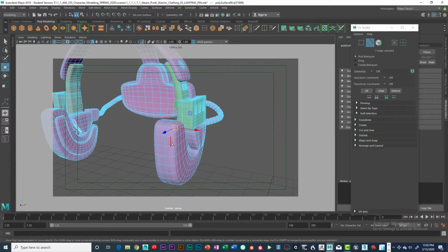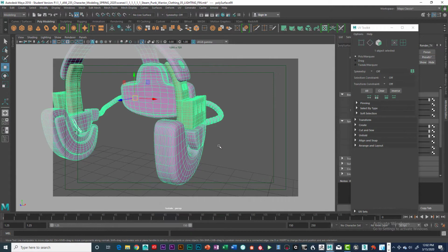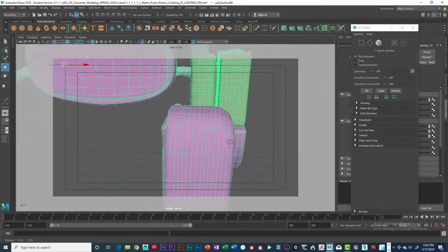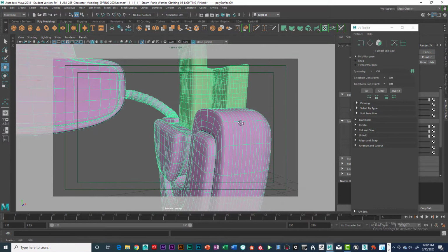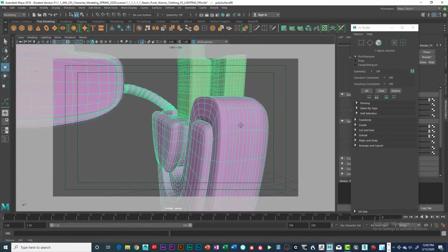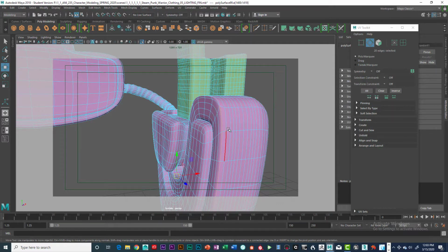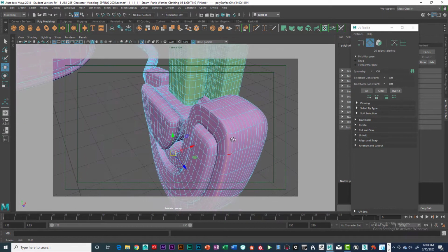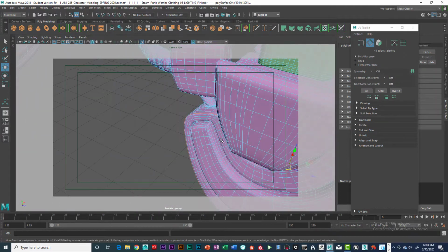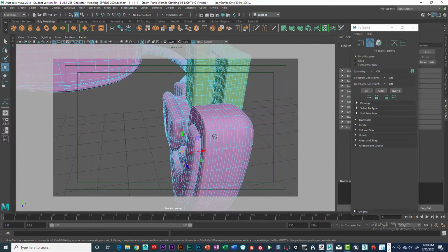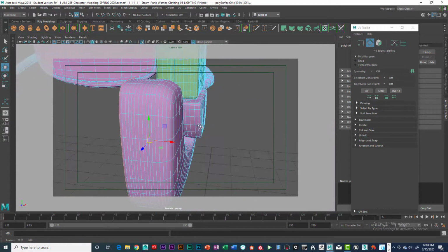Another thing about UV mapping and cutting everything up into seams is that anything that has a 90-degree angle is a natural seam cut, and you want to cut there. What does that mean? What is a 90-degree angle? Well, it's something like this. It's an edge that goes all the way around. That's why it's so important that I'm always talking about edge loops. Now this particular object is very complex, so it might take a little bit for me to get all those edge loops in there.